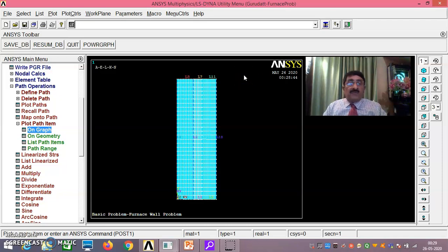Temperature plot, flux plot and vector plot are very important, by which you will know what exactly is flowing and what exactly is happening. That means heat flowing from the high temperature to the lower temperature region. You can clearly view it in a vector plot. Okay, heat flux plot, temperature plot, these are all the quantities of interest, particularly in thermal analysis.